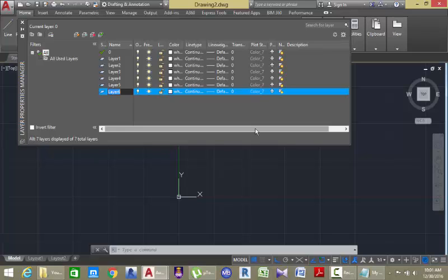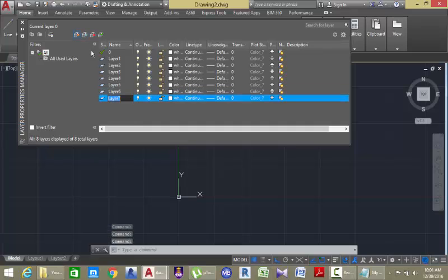So if you put some of the lines in different layers, that can help you to freeze the lines that you don't want to use at the moment. Then when you're done, you take all your objects and put them into a single layer. So now let's create. I'm just going to create these 6 layers as temporary layers. I'm going to use them during the drawing process when necessary. Then we're going to create 1 more, which we can name as edge.